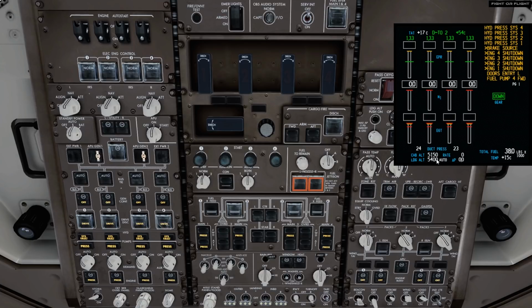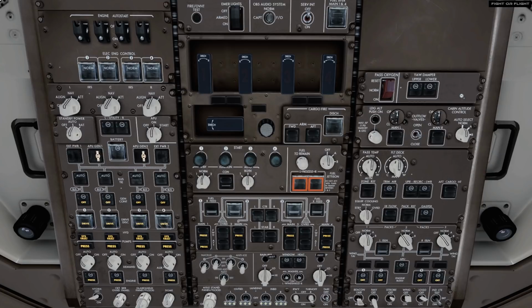However, the 747 FCOM states that if your destination airport elevation is between 8,000 and 10,000 feet, you should set this to manual and dial in 8,000 feet. Then, before the descent, set it back to auto. The manual outflow valve selectors are both off, and the valve indicators are pointing to open. Finally, the passenger oxygen switch is guarded, and the upper and lower yaw dampers are on.